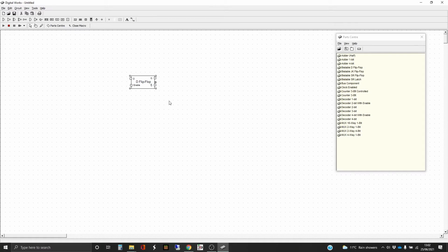If you don't understand what one of these is, then you've got other videos to look at and to work out. It's going to need to deal with a bus, so we're going to have a bus input. And I'm actually going to just do a line as if it were a bus. I'm going to stick an LED in here, even though it's part of a macro. If we're debugging, we've got problems, it might be useful to have that. So typically I create buses as a line and then tap off them, because that's how buses effectively work.